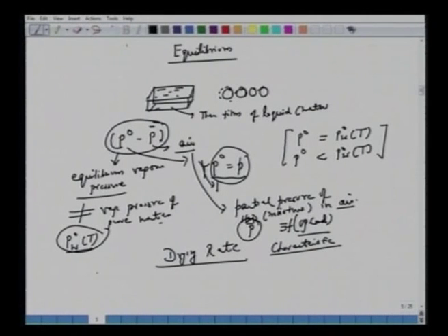So when solid starts, now water starts evaporating, as the solids start drying, this P0 will change. So this P0, what we are writing equilibrium pressure, of course temperature is fixed, but now this becomes time dependent, and you have P bar, assuming that P bar remains constant. That means the drying rate is a function of your moisture contents. So we will talk about this, how does now the partial pressure at the solid surface change with time as the solid is getting dried up.